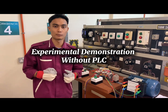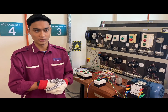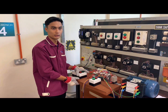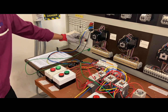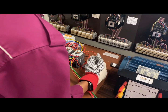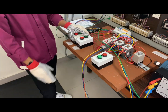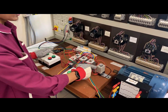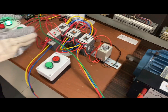So for this part, I will explain the experimental demonstration without PLC, which is the three-phase star delta with no PLC. So first we switch on the supply, and then we turn on the MCB or main switch, and then we set the timer to 5 seconds first, and then we push the push button and see the motor. So the motor is running until 5 seconds, and then it transfers to delta connection